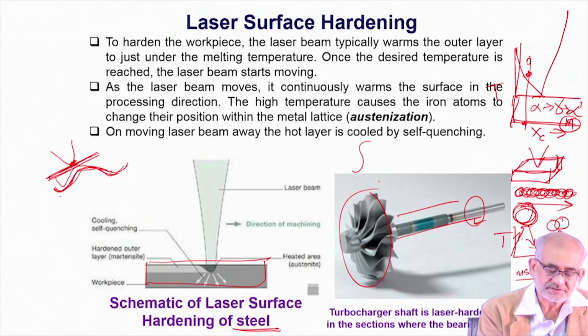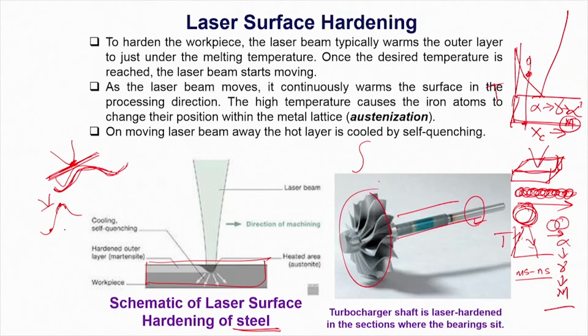So in the process, the heating cycle will be exactly the same. Otherwise, if the beam remains at this level and you have a curved surface, then obviously when this trough region is under the beam, the heating level will be much lower compared to the crest position, when the distance between the beam and the peak position is very close.